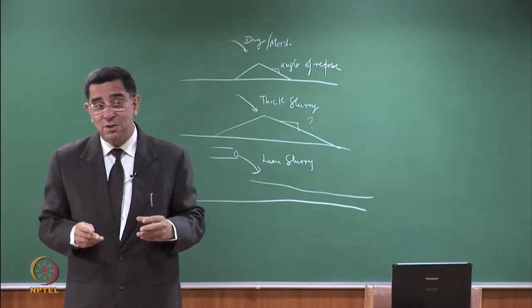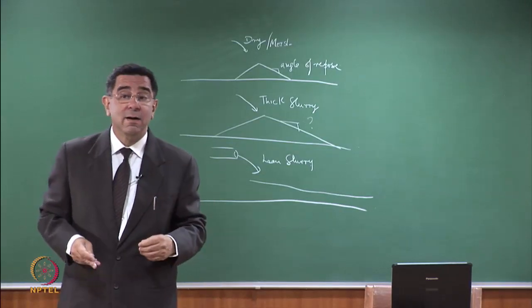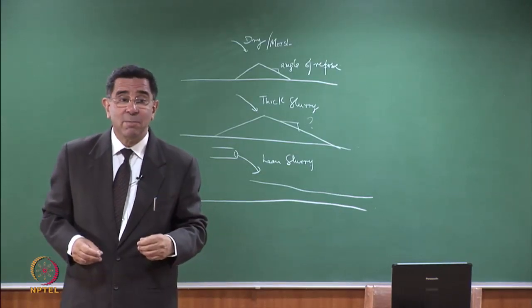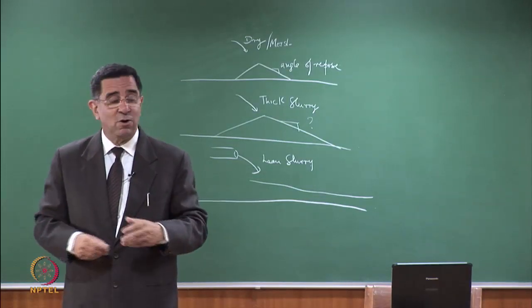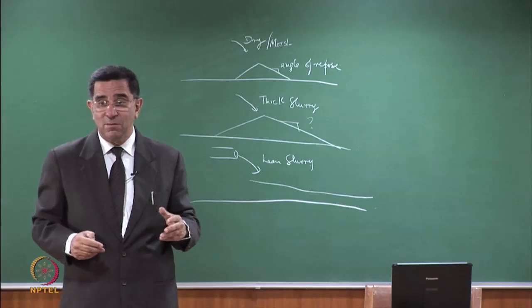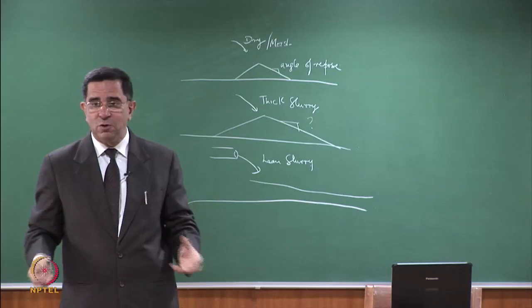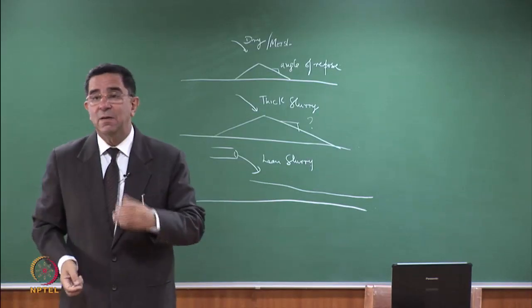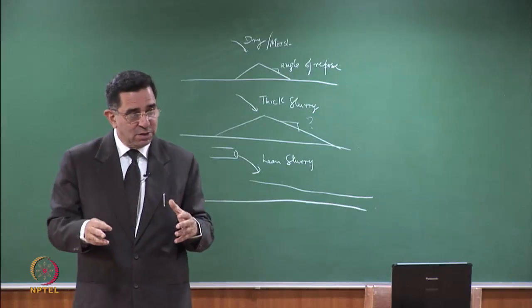So now the question is, how are you going to place the waste and how are you going to spread it? Dry powder or dry soil will not spread by itself, so you need to spread it. So how do we spread dry soil? We get a dozer and we spread it in layers, and if you want to increase the density because you want to store more material, I will compact it. So the higher the density for the same area, I can accommodate more material.